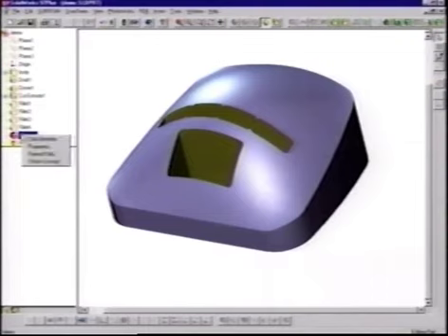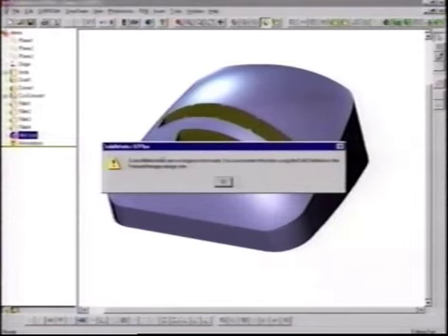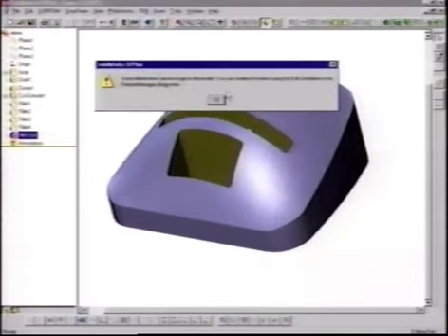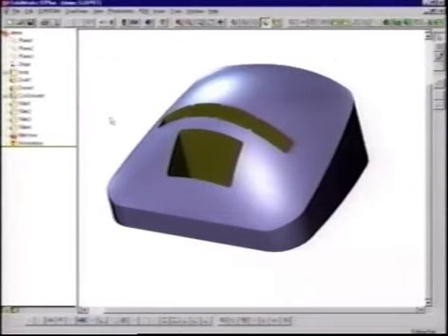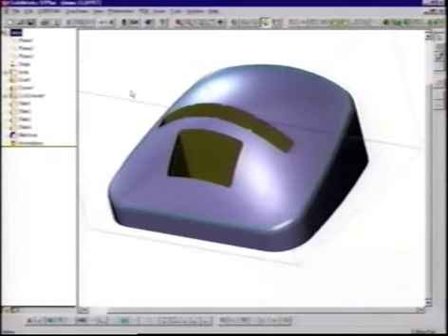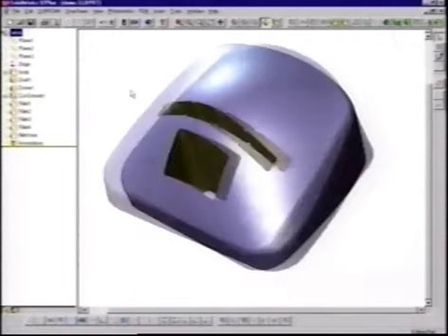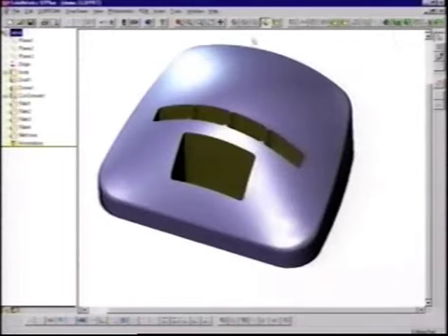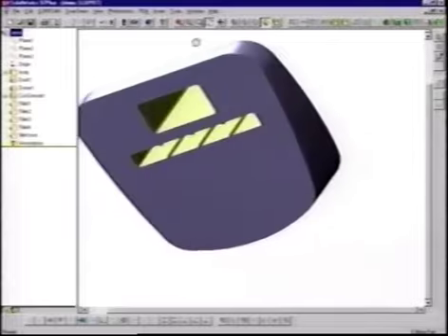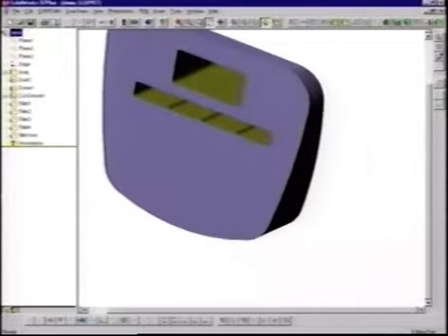So what Joe's able to do is select it with the right mouse button and go to the What's Wrong menu option. When it comes up, it's telling him that one of the edges that was filleted has gone away, and that's because we domed it away with the dome feature. Well, that's fine. One of the ways we can fix it is to simply grab the feature from the Feature Manager design tree and drag it right onto a brand new edge. So now you can see that front face is filleted just as it was before, and the red exclamation is now gone in the Feature Manager design tree. And again, editing your design is that simple in SolidWorks because it's a native Windows application.